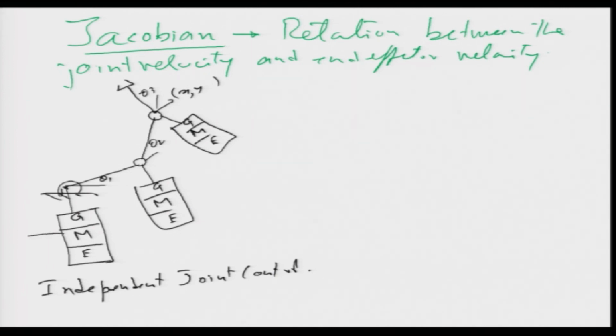If you want to move the end effector, say I want to move from here to here, how is it going to move? Essentially, inverse kinematics will tell me that at this position and orientation, what is the new theta 1 dash, then it will do theta 1 dash minus theta 1. So by using inverse kinematics I am going to find the difference between theta 1 dash and theta 1 and make that into some kind of an error of theta 1.